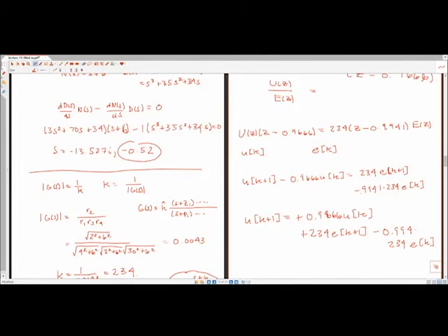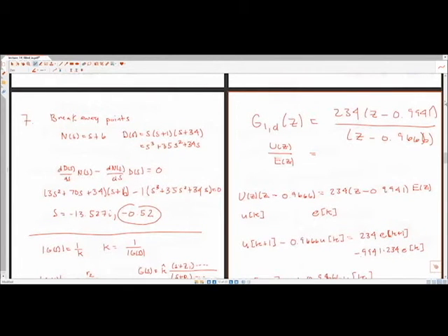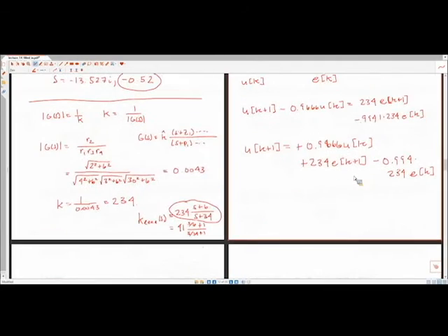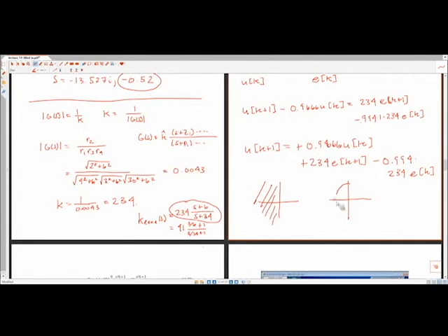You may also look and say, okay, the poles of this transfer function are in the right half plane, so how can that be? We said that this controller is stable because all the poles were in the left half plane, and now they've moved into the right half plane. That's a completely different story. In continuous time, the stable space in the complex plane is the left half plane, but in discrete time it's actually the unit disk. If your poles are inside it, it's stable, and if they're outside the unit disk, they're unstable. It's a completely different analysis method, again well beyond this class.